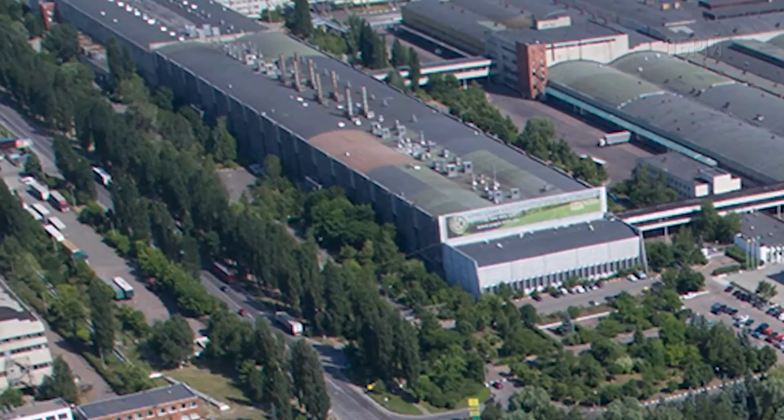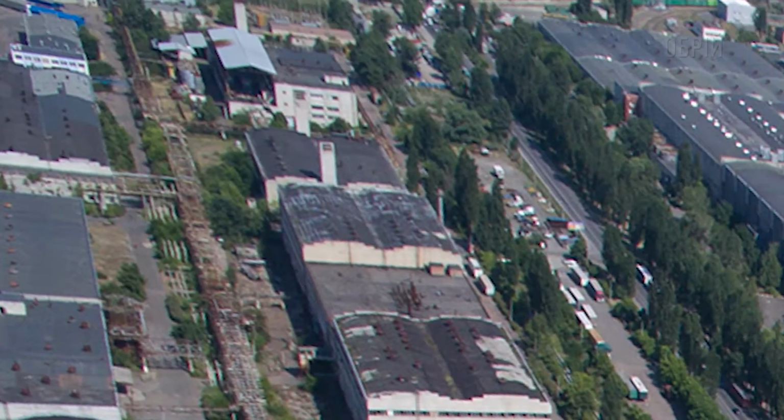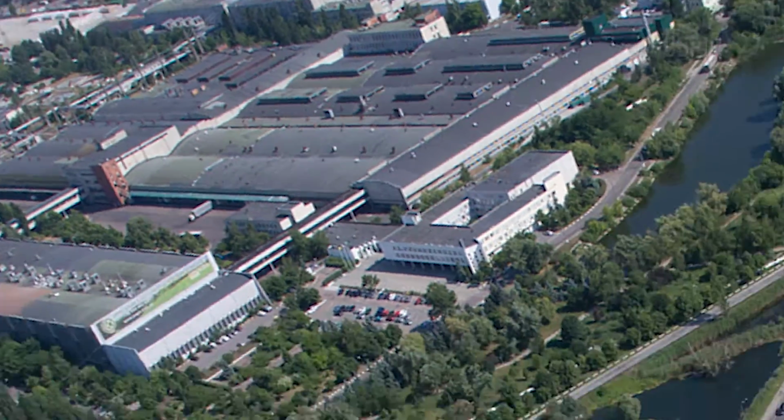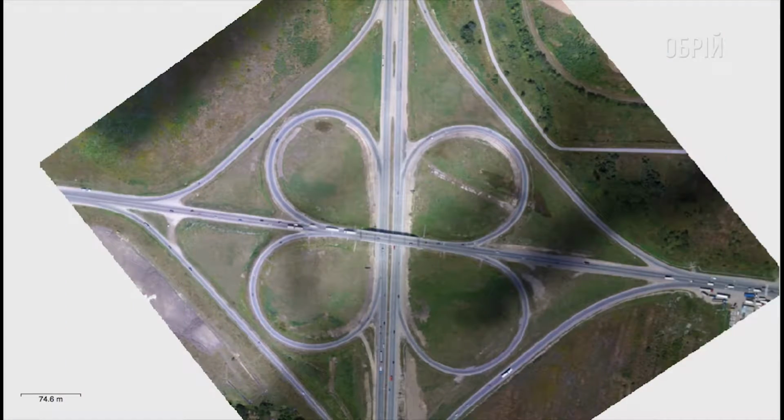If the survey photo is used for measurements, optical distortions take place. The closer to the edges, the bigger the distortions. The orthophoto plan lacks it. Any areas of the same length in nature will be equal in the orthophoto plan.